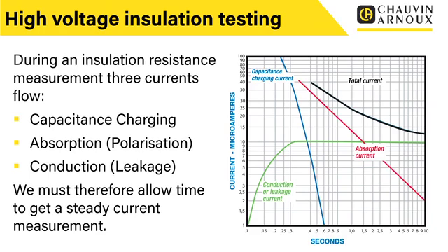Obviously using a DC test voltage, there will be a positive and a negative. Within that insulation, there will generally be a random alignment of all of these molecules within the equipment. When we place the insulation under test, there is a period of time where the insulation orientates itself and polarizes itself to that application of positive and negative.